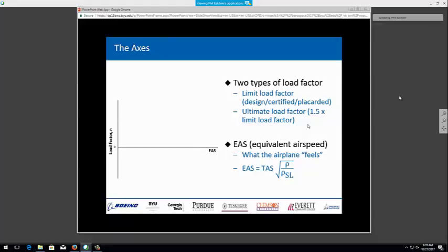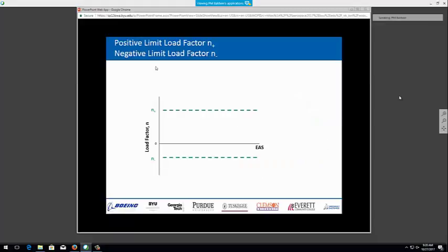So we put that all together, and we get the gust VN diagram, or the gust loads attached to the VN diagram. Load factors do represent the loads, but they've got to be multiplied by 1.5 yet to put in a safety factor. 1.5 is a lot for us. We may not need that for the small UAVs that we're talking about.